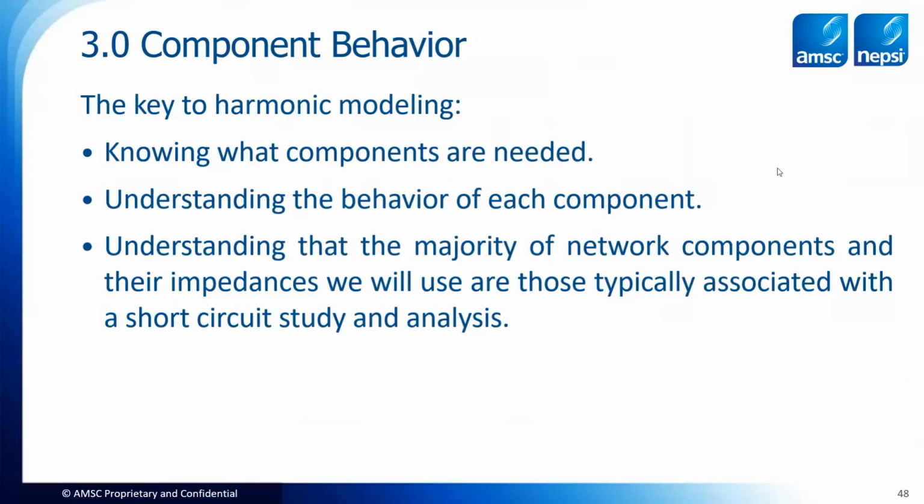Again, key to harmonic modeling: knowing what components are needed, understanding behavior of each component, understanding that the majority of network components and their impedances we'll use are those typically associated with a short circuit study. Okay? It's kind of interesting. There's a lot of crossover between short circuit and harmonics in terms of the input data, and you'll see that.